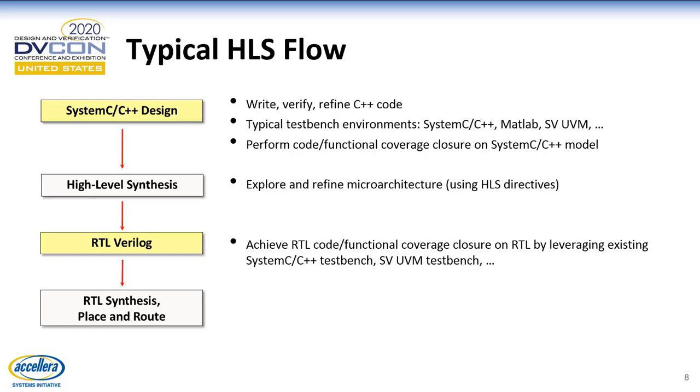and does most of the verification and refinement and debugging at this level. And typically, the test bench environments used at this level will be SystemC test benches, MATLAB, or System Verilog UVM. And you can do C code and functional coverage closure here on the SystemC model. And this pays off because basically all the work that you do to do verification and code and functional coverage closure up here sort of transfers to the RTL that gets generated later.